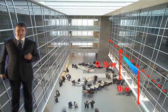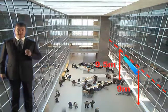Right, let's go through this exercise then. The first question was, where should the base of the smoke layer be allowed to descend to? Well, the base of the smoke layer should be at least 0.5 metres above any opening that needs protecting. And in this case, it seems reasonable to protect the first floor opening against fire on the ground floor.